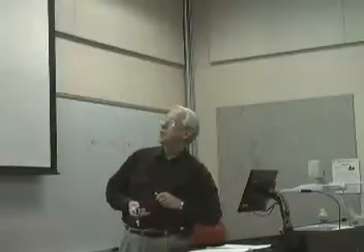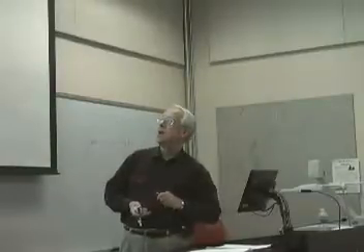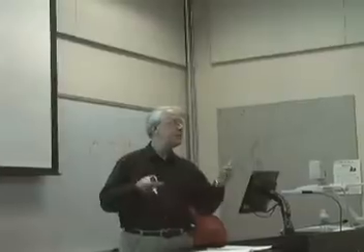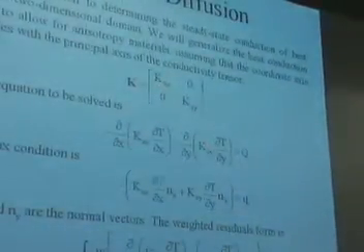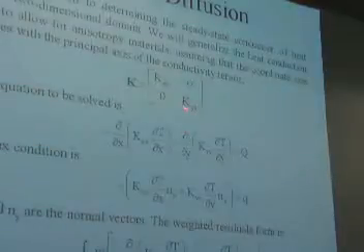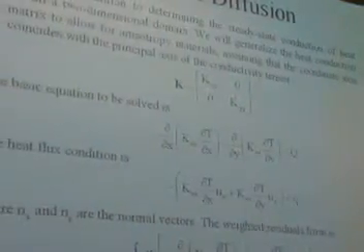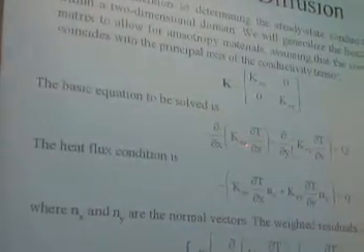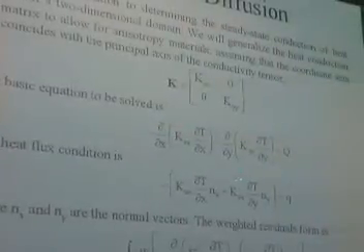Here's a simple equation. Assume that I've got a conductivity in heat transfer simply constant. Maybe I've got variable conductivity in a material, so I can actually load in the variation in the conductivity that would be setting here and here. This would be the governing equation. That's a Poisson equation. Right? So here is the boundary condition.